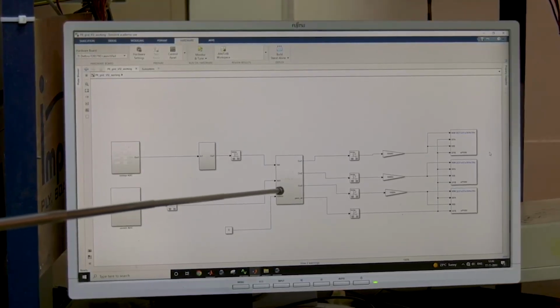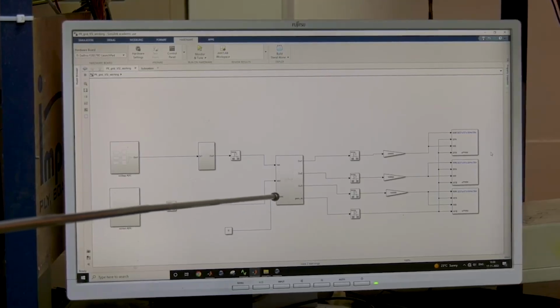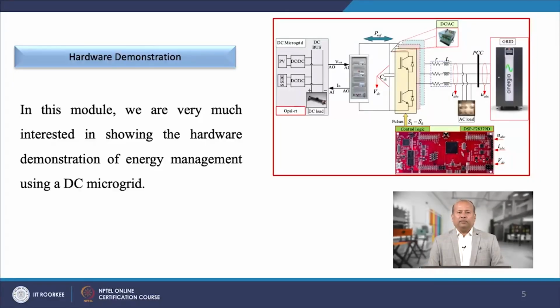Before configuring the launchpad type, ensure that the required software is installed in the system as per the guidelines given by MathWorks. After the configuration, the ADC pins must be configured to get physical signals into the DSP controller.